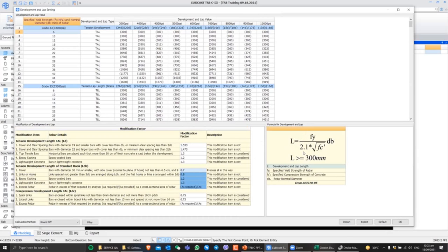You won't be using this because again, we have a preset quantities dun sa general notes na katabulate na po from the designer. So, ano po yung gagawin natin? So, ang gagawin na lang natin is to type the actual value. Okay? For example, I want to change the development length in tension based on the general notes. The first thing to do is find the rebar size. So, let's say it's diameter 12. Tapos po, ano yung concrete grade niya? No? So maybe it's 4,000 PSI.